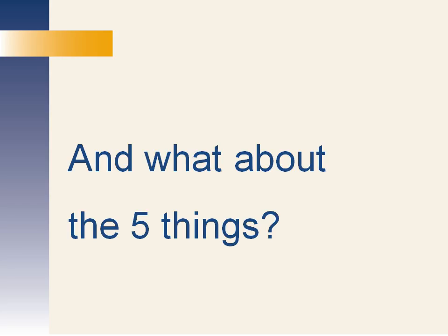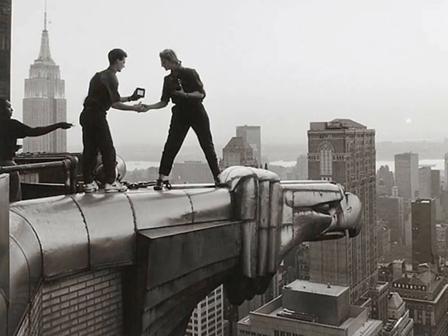In this era, we have essentially the same story on all the 5 things as we had before. Very few were addressed, but for most buildings, all of the implicit compensating factors continued to exist as well. There were, however, notable and important exceptions. Landmark structures like the Empire State Building, Manhattan Tower, and Chrysler Building approached and exceeded 1,000 feet in height, and they did this without any clear understanding of system buckling, secondary effects in frames, and effective length factors. Certainly those compensating factors were now beginning to be tested by these designs.